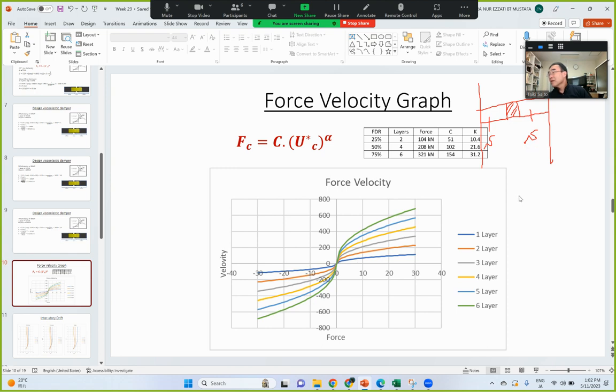We design the damper to yield first. So if the damper yields, the steel beam is okay, no damage, right? Yes. But in this viscous damper, the damping force is very high. So I think in some cases I observed yielding at the steel beam. Yes, Sensei.